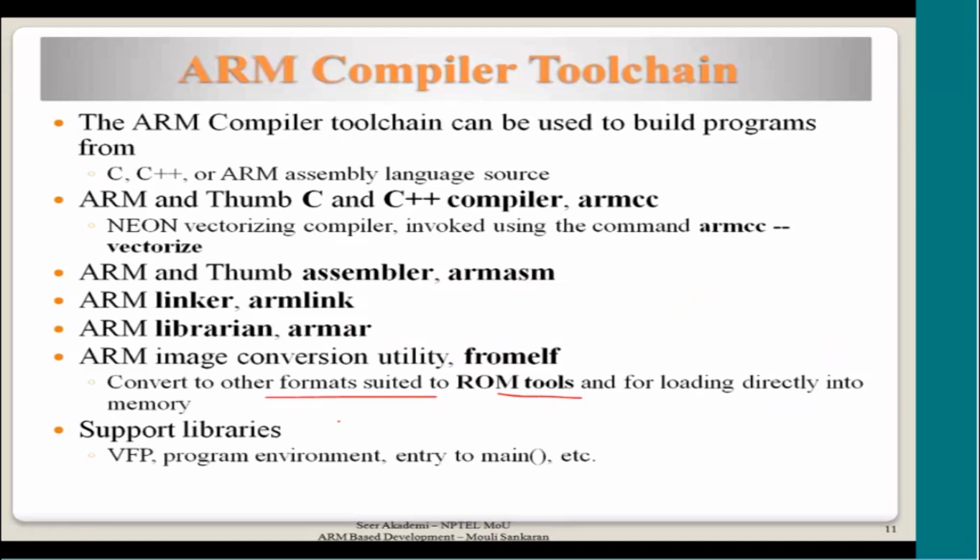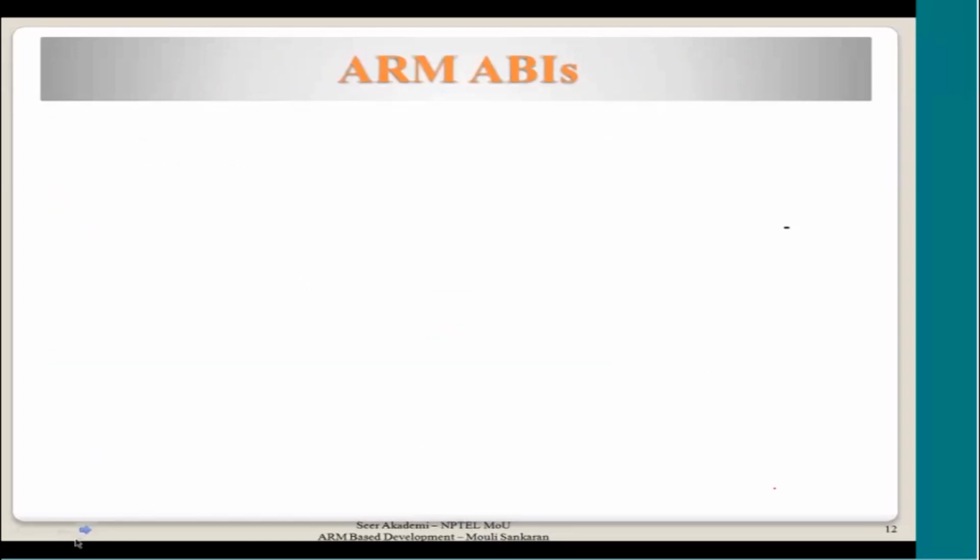Okay, support libraries, as I mentioned, some of the functions or VFP related things, or even calling a main routine. Before that, there are so many things. You remember, I mentioned that the stack pointer for all the modes has to be initialized. So that could be a library, and we can feed that information also, or it could be done by the OS. So the OS also may be integrated. Those things also have to be finally integrated with your application, and then finally the executable is got, and that will be put into the ROM or flash using these tools.